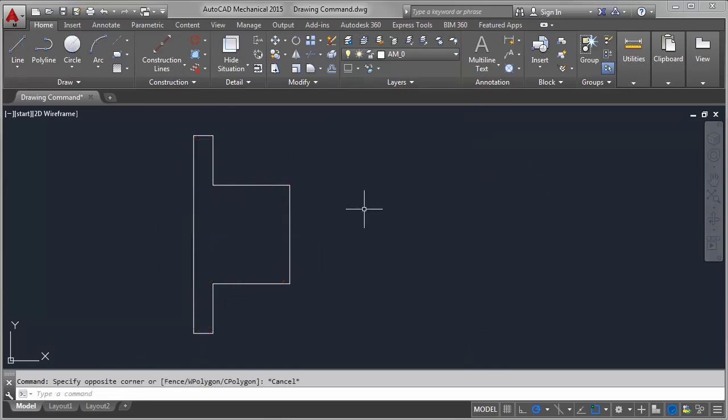Now let's begin. I'll start with adding a center line. I click the command, select the start and end point, and we have a center line. The command we just used is special to AutoCAD Mechanical and comes with a big advantage. Have you noticed the automatically created centerline layer? That's where AutoCAD Mechanical places all centerlines. You don't have to create or change layers yourself anymore. AutoCAD Mechanical does all the layer management for you.